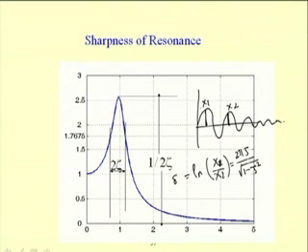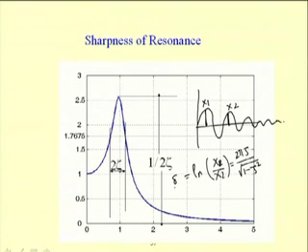Using one accelerometer or vibrometer, one can find the free vibration response of the system. After getting the free vibration response, one can find the successive amplitudes, and from that one can obtain the logarithmic decrement of the system, and then find the damping of the system. If the damping is very small, one can neglect zeta square with respect to 1. So, one can write the logarithmic decrement equal to 2 pi zeta, and one can easily get zeta from that.